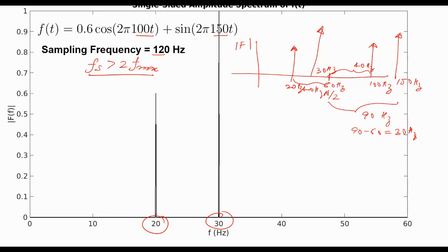Now one may ask, how can I know what frequency is going to come in the signal? In fact, this is true for any measurement. So let's say you want to measure temperature, then you must have an idea of the typical range of temperature you are expecting to choose the appropriate thermocouple, let's say. Similarly, for making measurements, you must know an estimate of the frequencies in the true signal, and based on that you must choose your sampling frequency.